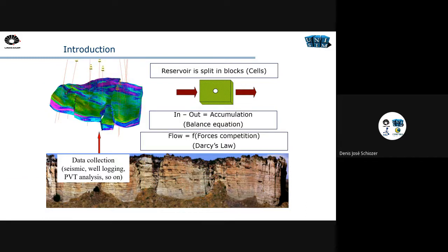If you have, as I put here, a producer producing here, right, and an injector injecting here, I'm increasing the pressure here, and I'm decreasing the pressure here as I put the producer here and the injector here. As I have a gradient in pressure, the fluid is moving in the horizontal direction because I have a higher pressure here and a lower pressure here. So I'm trying to mimic this behavior in each of the blocks of the simulation model here, okay?